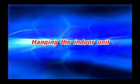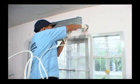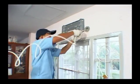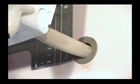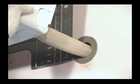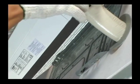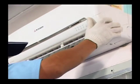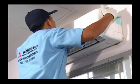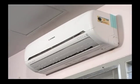Hanging the indoor unit. First, insert the bunch of the tied wires, the refrigerant pipes and the PVC pipe into the hole carefully to prevent damage, which could cause water leaks at the seal. Then hook the upper part of the indoor unit to the upper part of the installation plate and lift the lower part of the unit until it can securely lock to the lower part of the plate. Make sure that the unit is put right into its place.